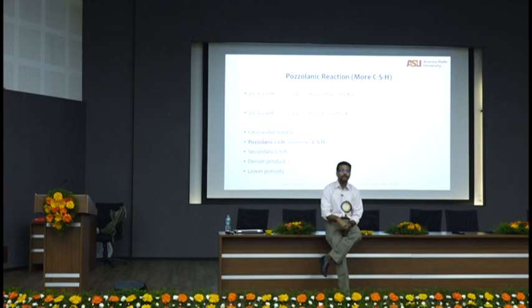So, acceptable size of fly ash particle? There are different ranges. The rule of thumb is that fly ash particles should be of the size of cement particles, in that range, so that your cumulative particle size distribution is not significantly different.